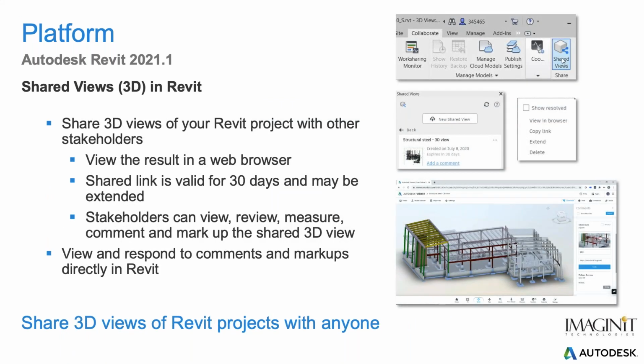This is a really cool new feature as well, shared 3D views in Revit. So all of us have probably worked with someone who isn't part of your BIM 360 hub or who just isn't a Revit user or who maybe shouldn't get a hold of a whole Revit model. This new function is called shared 3D views or just shared views, but you can only share 3D views. So basically what you can do here is you can share a 3D view via a web browser with some other stakeholder in the project.